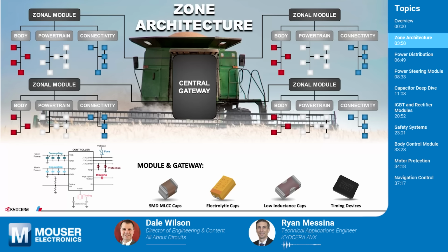But this specific example shows a complex piece of farm machinery optimized with zonal architecture. There can be many more zones than the 4 zones you see here. But regardless, you have a zonal architectural module, basically an ECU, like I said before, and drive electronics to the powertrain, maybe wheels, motors, maybe height, pitch stabilization, the host vehicle, or cutting arms. There are a variety of different applications that can be utilized.